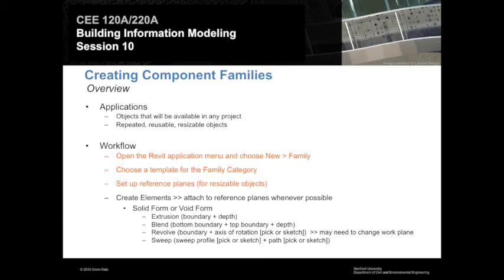Okay, so as opposed to creating an in-place component, which is locked into that one project, you open something called a family template, which opens a shell where you can do that same operation. Okay, but by putting it in this external shell, then you can go ahead and copy it into other projects. So let's show you what I mean. It all starts with this notion of really just saying that you want to create a new family and choosing a template.